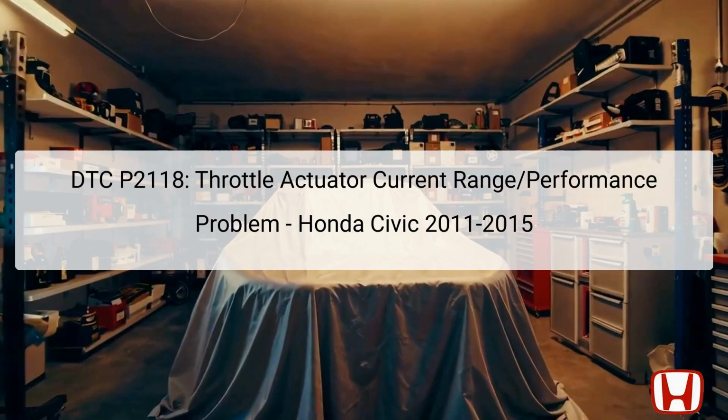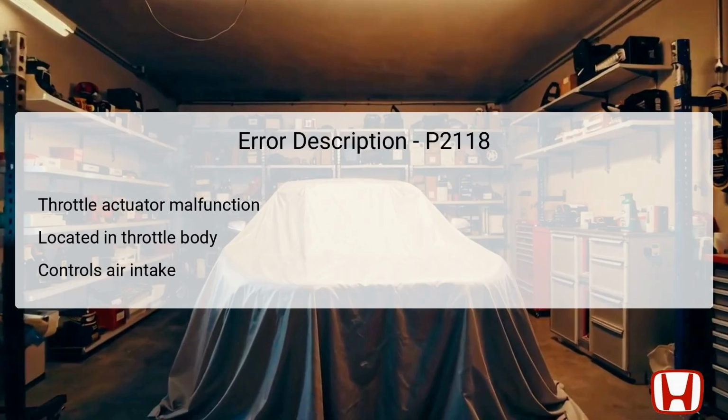The throttle actuator is integral to the vehicle's throttle body, which controls the airflow into the engine. By modulating this incoming air, it directly influences engine performance, efficiency, and responsiveness. When a malfunction occurs, it can cause various performance issues such as hesitation during acceleration or a check engine light illumination. The throttle body is usually positioned between the air intake and the engine's intake manifold.